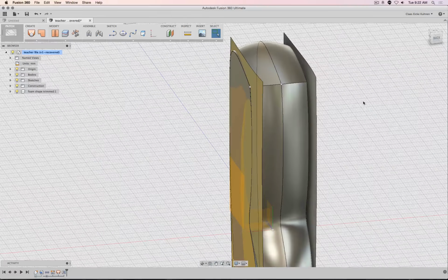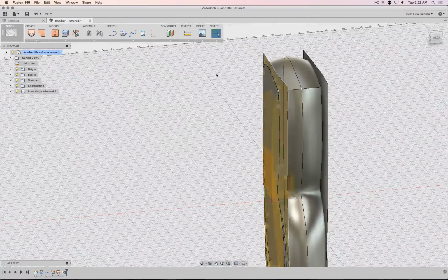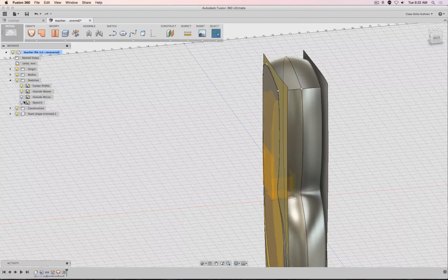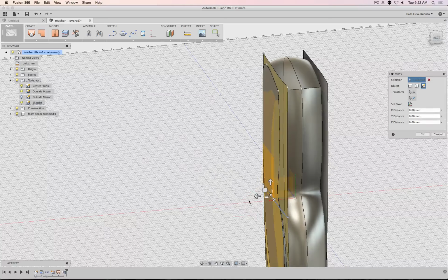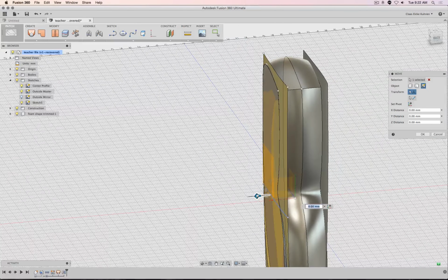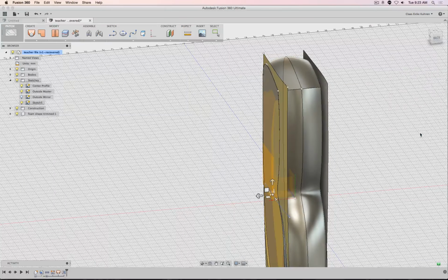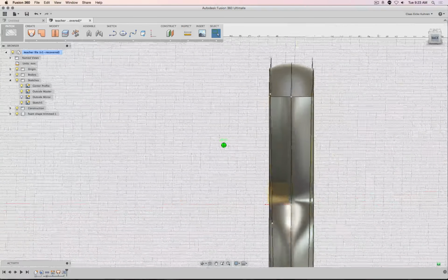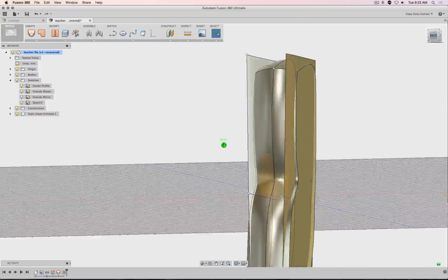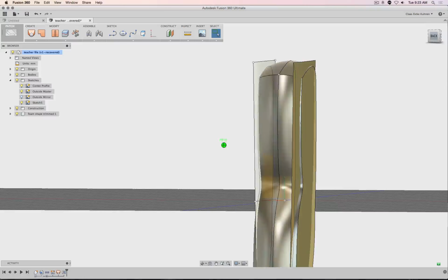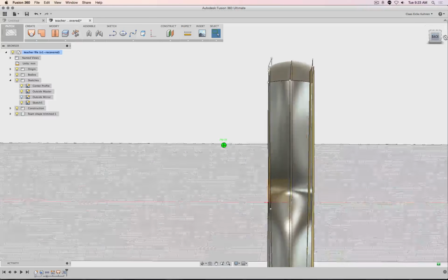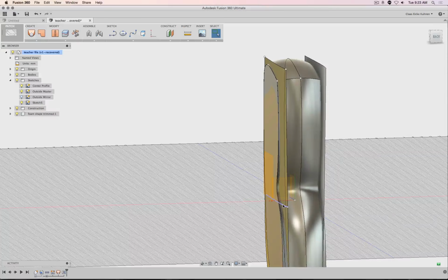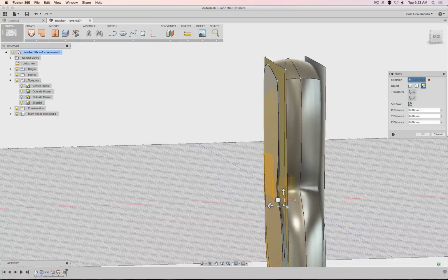That means maybe this second sketch I simply have to move in a little bit. This one here. Okay. Move. Just, let's see, millimeter might be a lot. Yeah, but there we can see what it actually did. You see nicely also this sketch drives the surface and then the mirror drives the surface. Pretty nice. So let's go back.